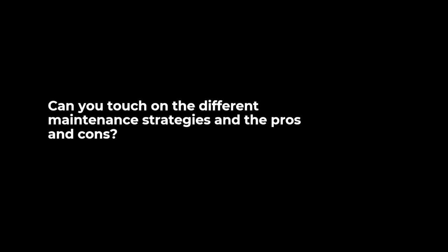Now, obviously, all of us would like to think that reactive maintenance is bad or preventative maintenance is bad and you have to move up the curve. While it is true that predictive maintenance is probably the best tool that you'd use for all of your critical equipment, it is not wrong to use other maintenance strategies as a part of your overall maintenance goal, because there's some equipment which you may not want to use a predictive tool for to be easy to swap out and easy to change.